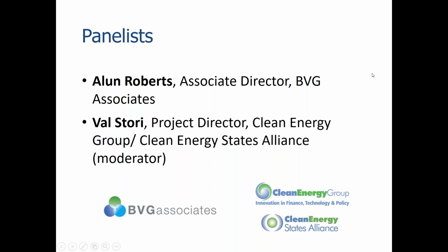I guess you're talking about an offshore tower. Certainly for the V164, I showed the picture. I think the base of the tower, lower tower section, is 7 meters. Your export from the factory is probably done horizontally in 3 sections, and then at the installation port they'll be assembled into a single vertical section for installation. A 7 meter tower width is probably beyond most road transport, and so this is the difficulty: that kind of component is too difficult to move on the road. If it's possible, then great, but generally speaking, you're looking at coastal facilities.